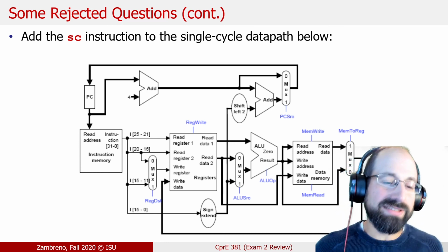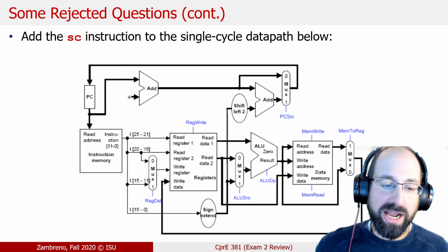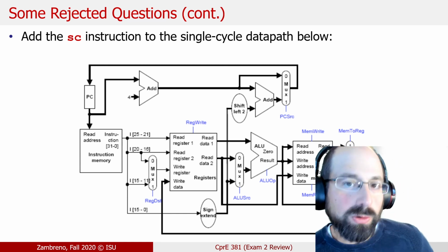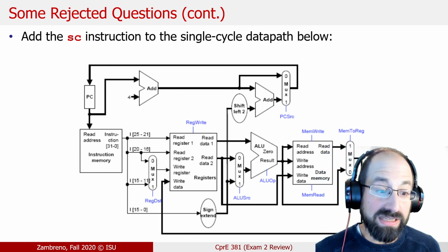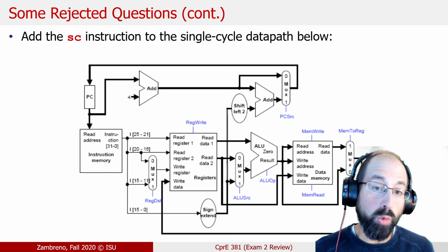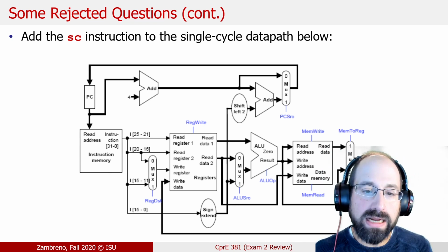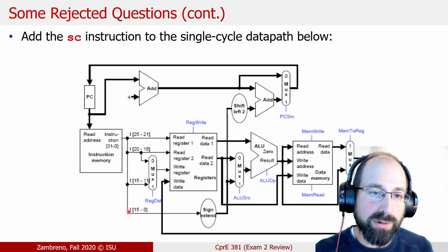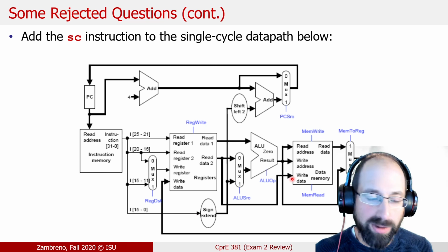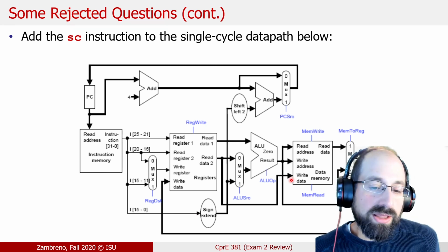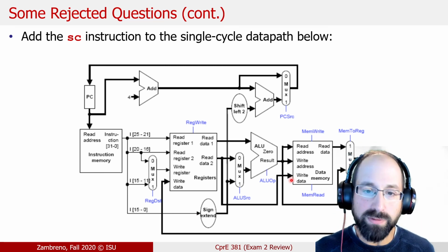The name of the instruction is ambiguous, and it's pointed out in the chat as well. If it was store a constant into memory, I would definitely need to provide more context here, right? Where in memory, where's the address getting encoded? If it was store constant into memory, we could do it. We would just need a way to get from this immediate type directly to the right data port. We would need to instrument that. Adding a mux there would be part of your solution.